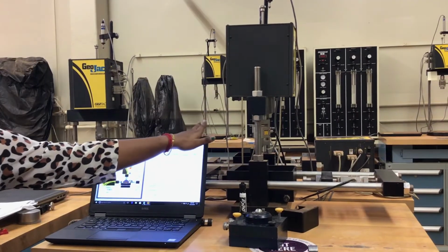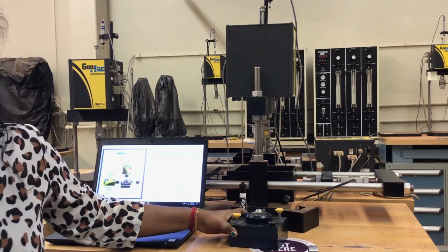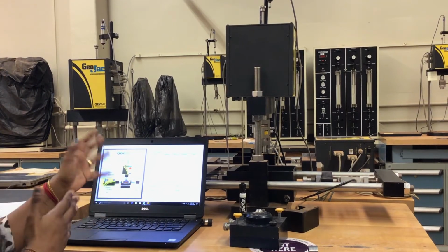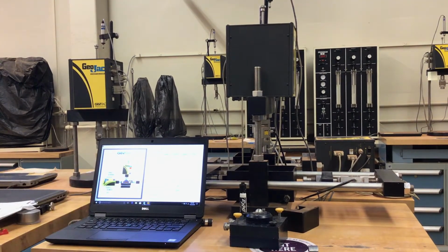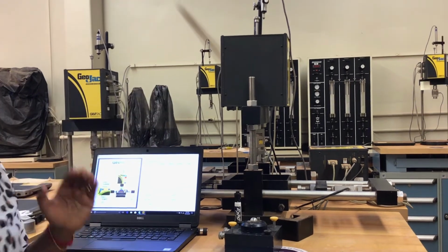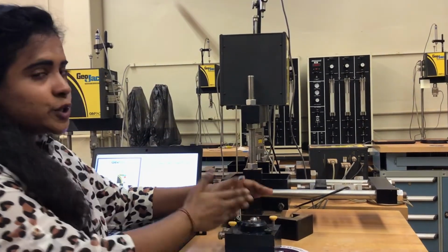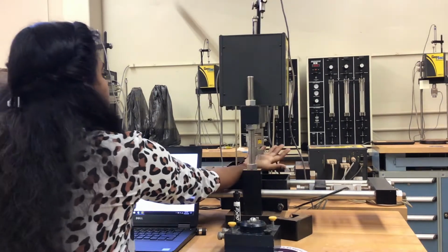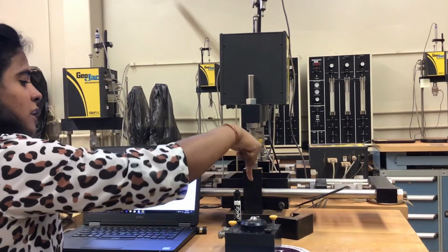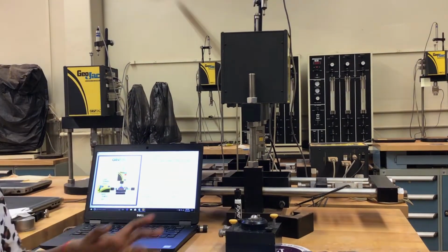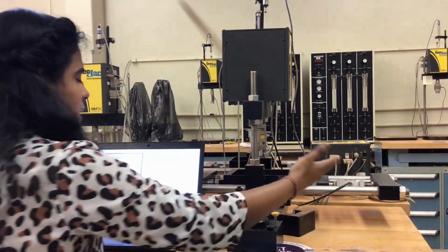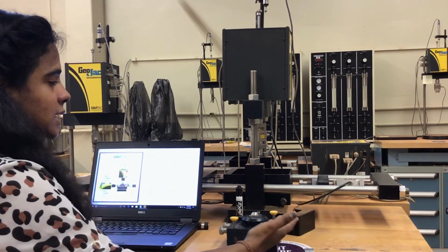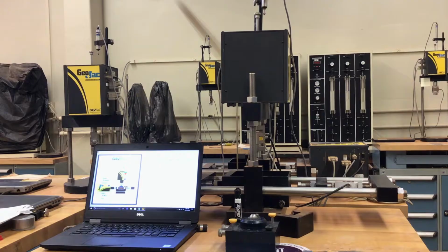This is the automated system we will be using for conducting this direct shear test. So before conducting the test, we will be calibrating the one sensor and then the load cells we have. So one sensor is used for measuring the displacement, initially how much your soil is settling. Then we will be using another sensor for the vertical load, which will be the normal load we will be applying. From that we can find the normal stress. The other one will be the horizontal load cell, where we will be shearing this specimen. So this load cell will move horizontally. So from that we can get the shear stress.